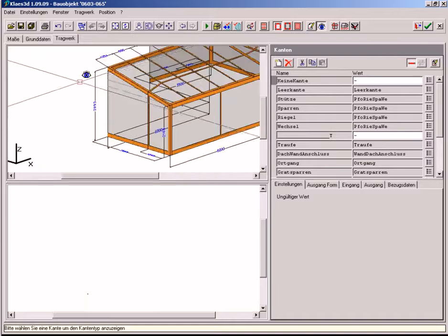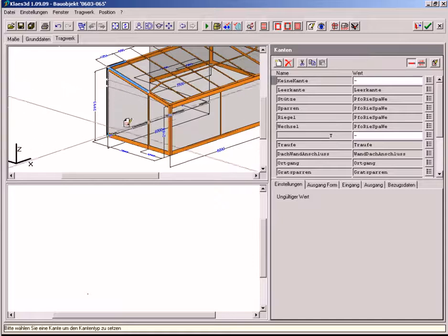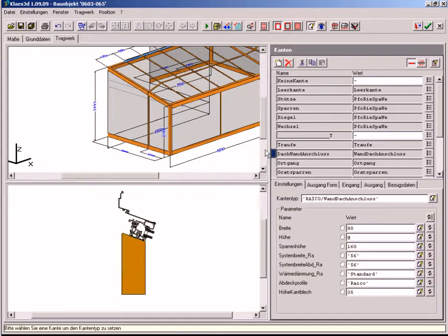The required roof member profiles are now set to the new construction lines. Now, the old construction lines which are no longer needed are deleted. The roof panel is replaced by a wall junction, the post by a wall backing, and the rafter becomes an edge rafter.